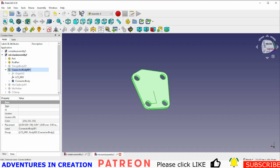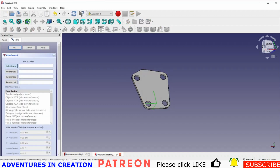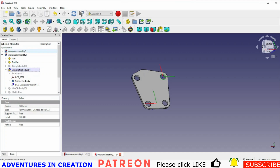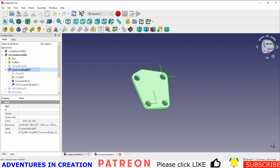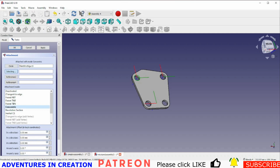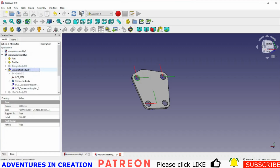So again, my connector body is selected. I'm going to say new coordinate system, connector body 1, and I'm going to make this one concentric, say apply, and say OK. Connector body again, select it, new coordinate system, connector body 2, pop that on that one, say apply, say OK, and you got it.